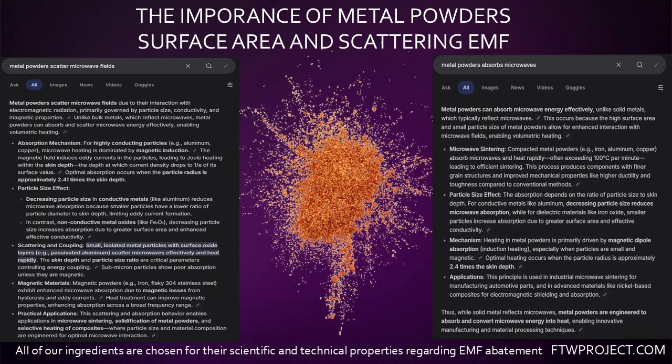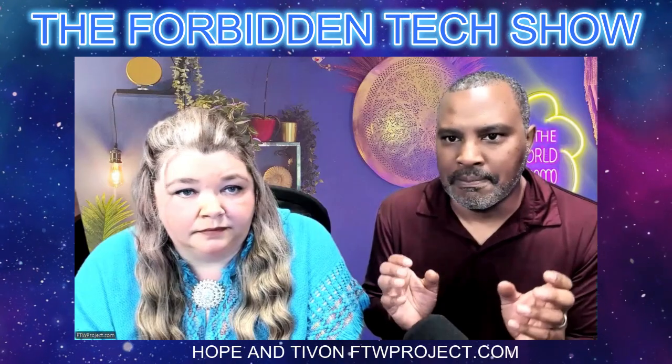Now the drawback is, you might ask yourself, why isn't everyone using powders then? A lot of it is down to access or knowledge for one, then access to the key materials that are powders of a certain size, and also the cost. Powders are a lot more expensive, but the trade-off is that you don't need a kilogram or 2 pounds of metal shavings when you can do it in a teaspoon of powder, because its surface area is much, much higher.